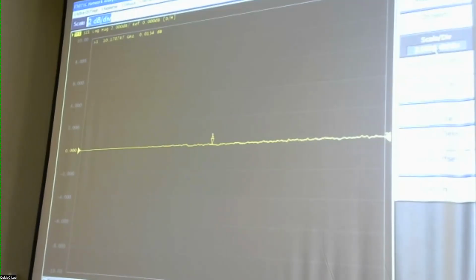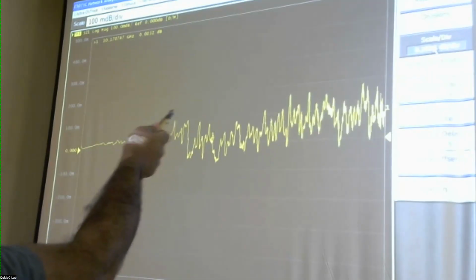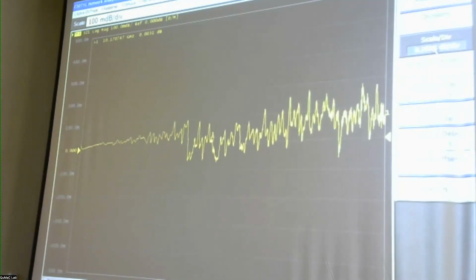Let's zoom in a little bit. One intuition you have to develop is to look at something like this and realize whether something is wrong or not. This is perfectly fine, but if someone quickly looks at this, they might say, "Oh, this is a horrible cable, transmission is going on over this." But it's a tiny fluctuation. And usually at higher frequencies, it's always going to happen, both because at higher frequencies all your devices' tolerances are not very precise, and the measurement also usually becomes harder and less accurate.